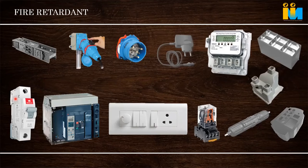Moreover, those materials have a tendency, due to the fire retardant property, especially in semi-crystalline, to produce some fumes, and some amount of sediments will accumulate in the mold, blocking our air vents or the ejector pins. So they make the mold in such a way that a very, very huge amount of venting will be there. Some porous pins will be provided, so that if gas is accumulating, burning marks do not come. Even small black dots are a rejection for some of the major MCB manufacturers.